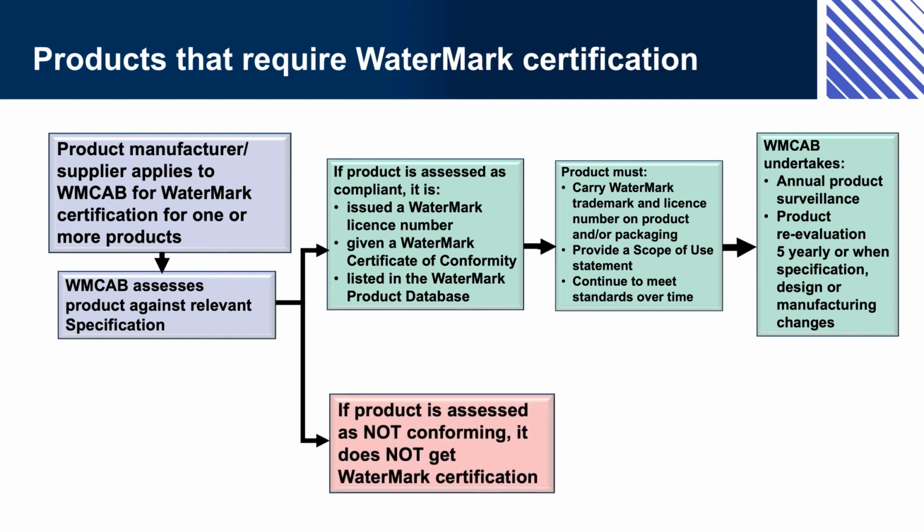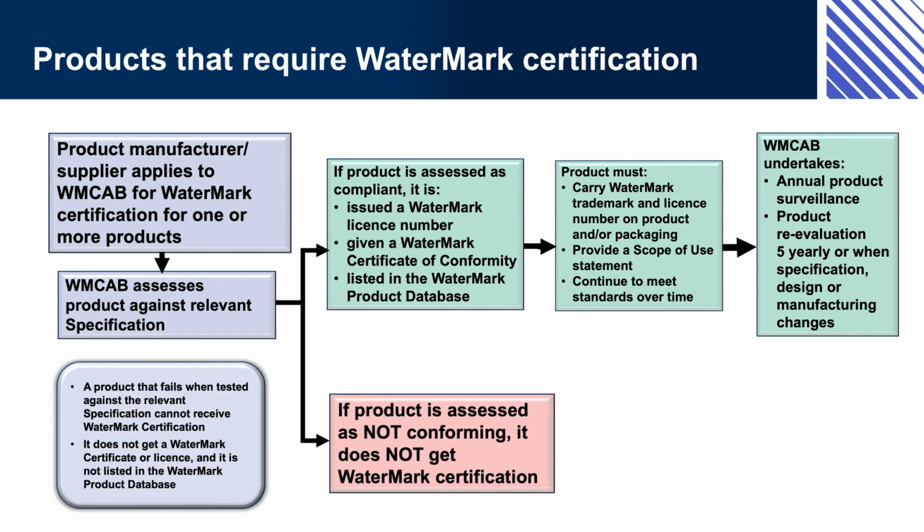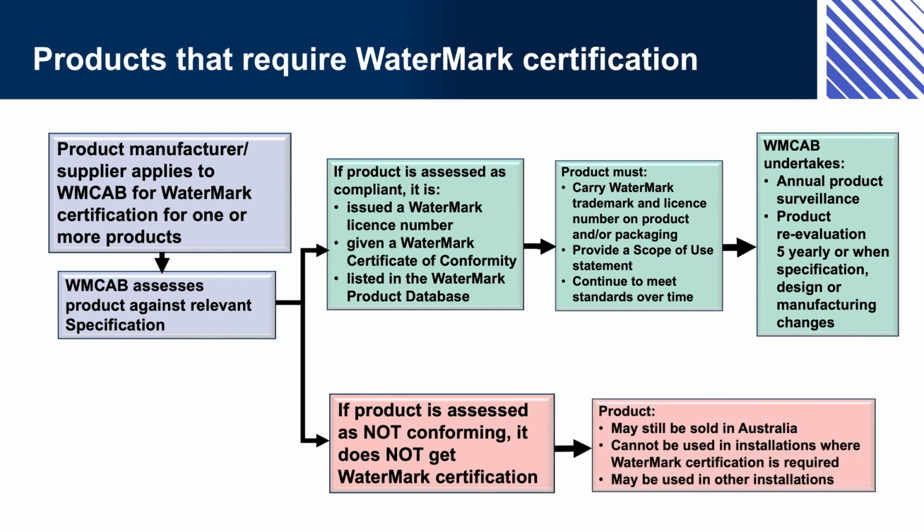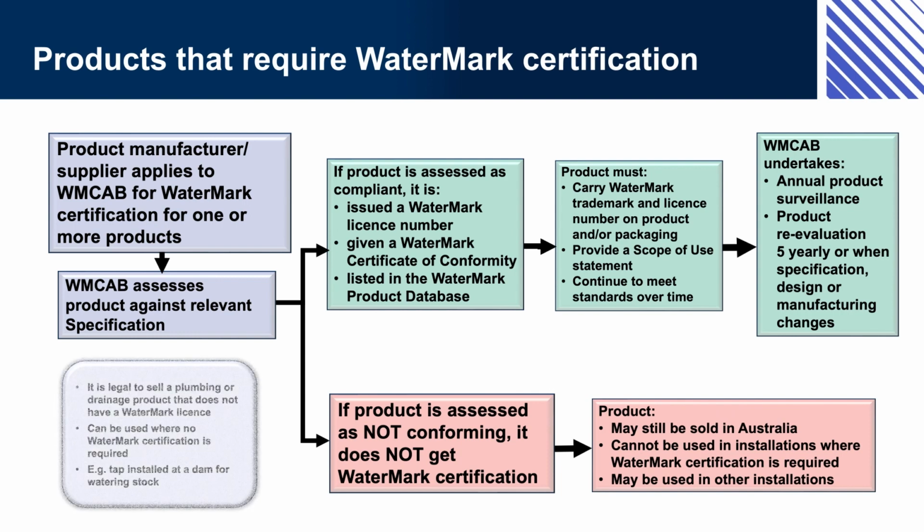If a product is assessed as not conforming, it does not get WaterMark certification. The product may still be sold in Australia, cannot be used in installations where WaterMark certification is required, but may be used in other installations. Note: it is legal to sell a plumbing or drainage product that does not have a WaterMark license. It can be used where no WaterMark certification is required, e.g., a tap installed at a dam for watering stock.